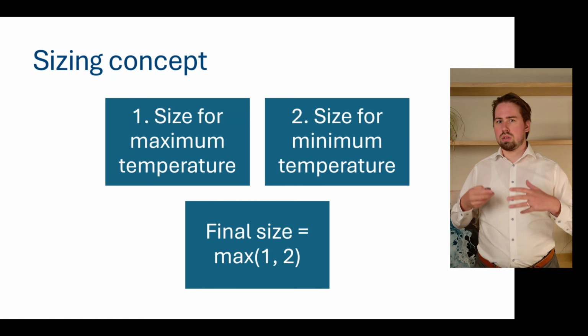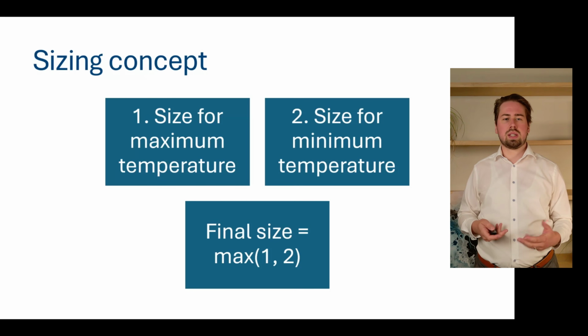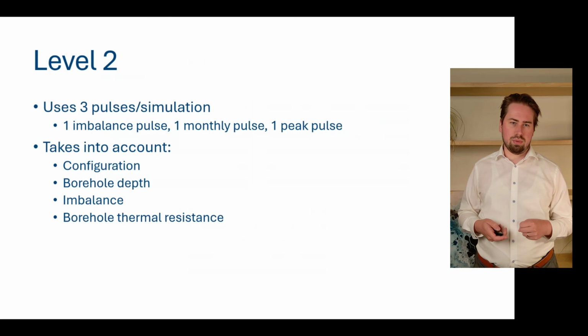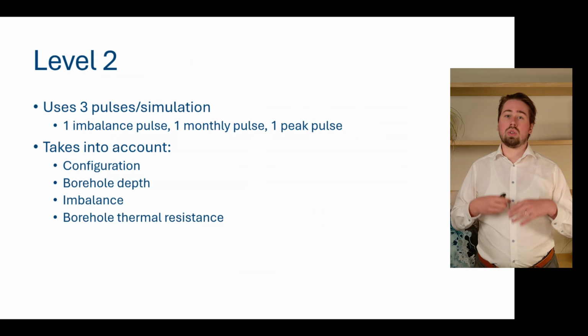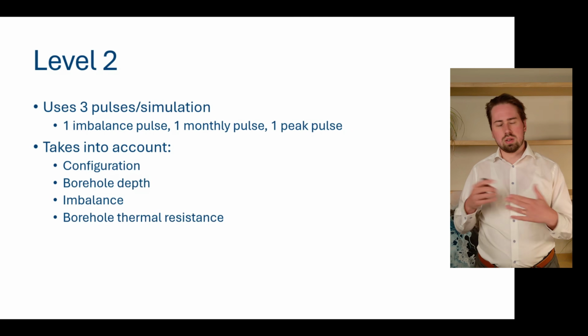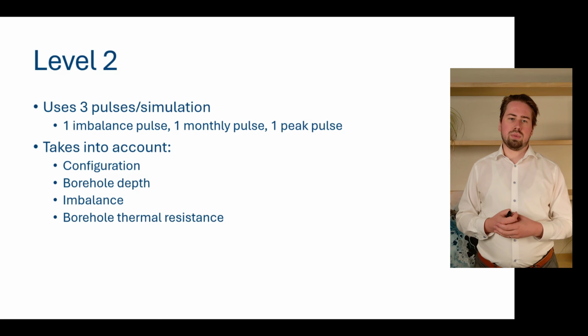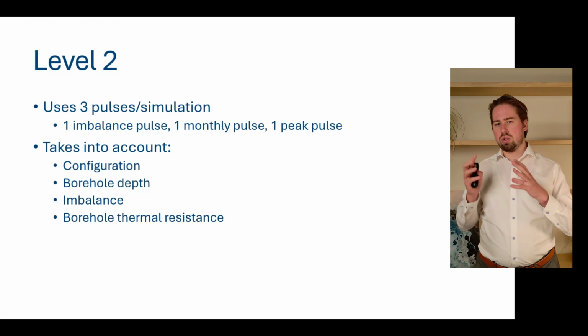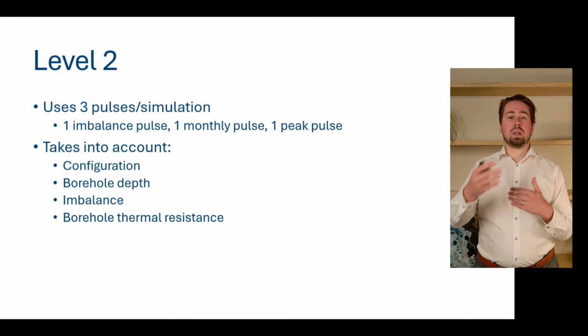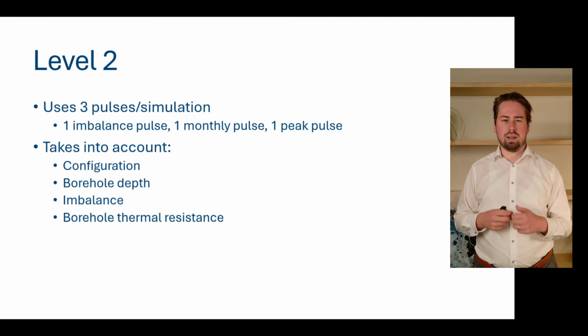And the first sizing level or level of accuracy that does that is the second level. And this is also called the ASHRAE sizing equation. It's a really common way of designing bore fields, and it basically uses 3 pulses for every simulation, every calculation of the required depth.